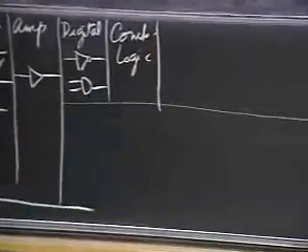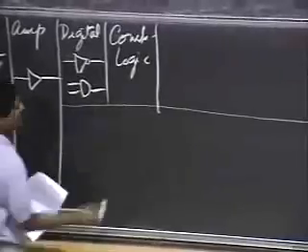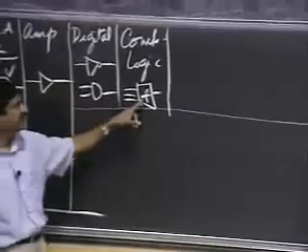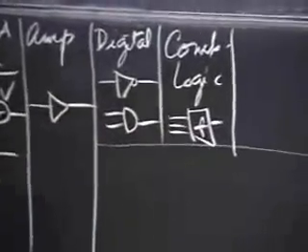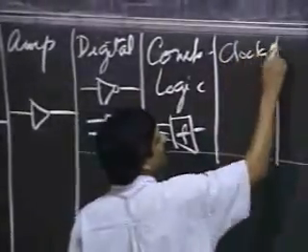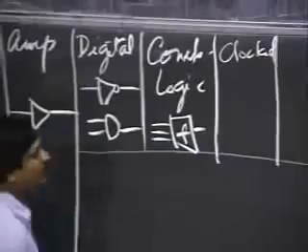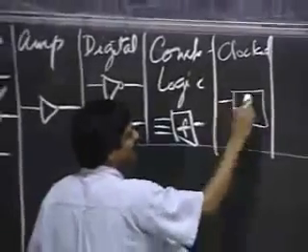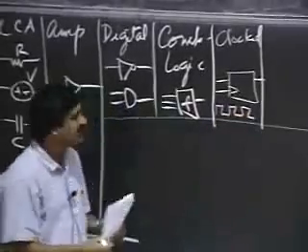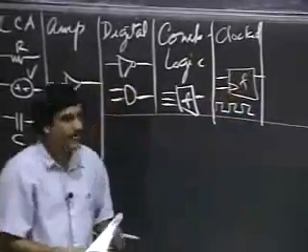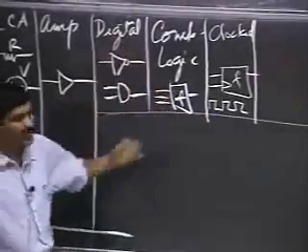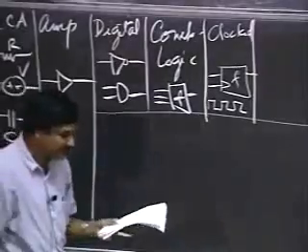All right, following the digital abstraction, we will superpose the combinational logic abstraction on top of that and define functional blocks that look like this: some inputs, some function, some outputs. The next abstraction on top of that will be the clocked digital abstraction, where we will have some notion of time introduced into the system. There'll be a clock that introduces time into the set of logic values that functions operate upon.